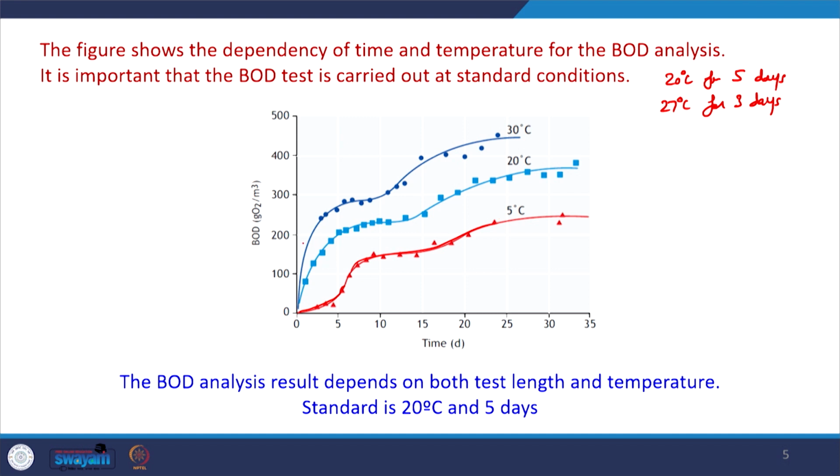So, the second part of demand is basically the carbonaceous plus nitrogenous. Here in this case we can see the demand is increasing. This section is the nitrogenous demand at 20 degrees centigrade. In this figure, this is the nitrogenous demand, whereas the lower part represents the carbonaceous demand.